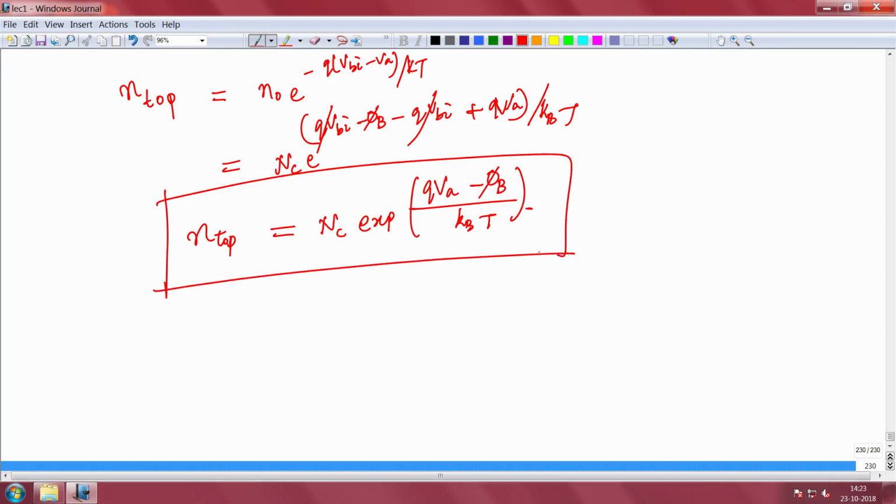It is a very small number because your applied voltage is very small, whereas the built-in Schottky barrier is pretty high. This quantity is very low actually. That is why we call the region W_d to be almost completely depleted. That is why it is a very low concentration.